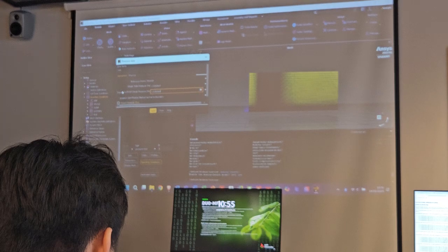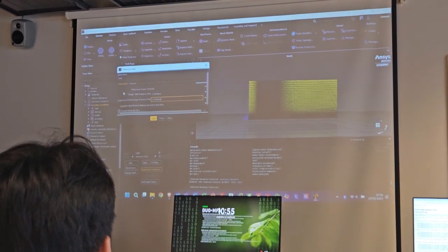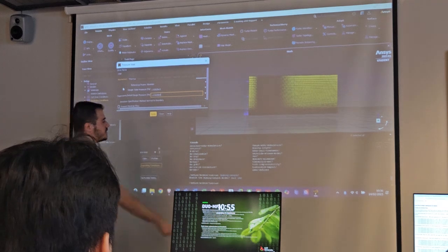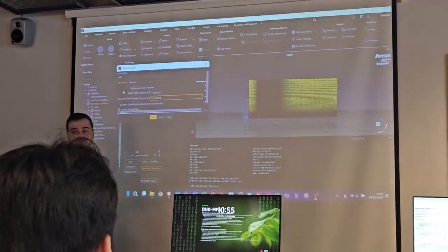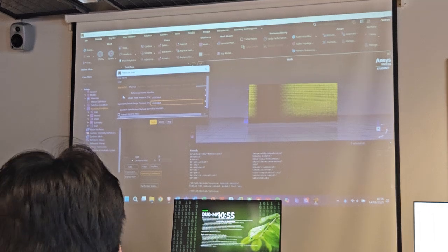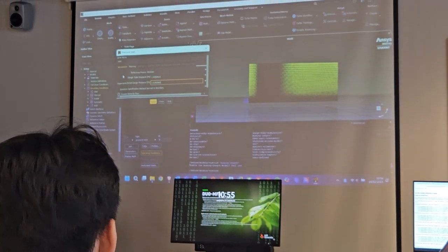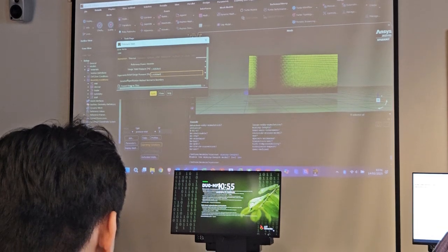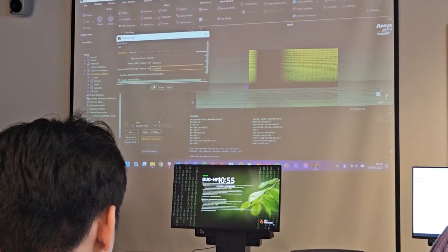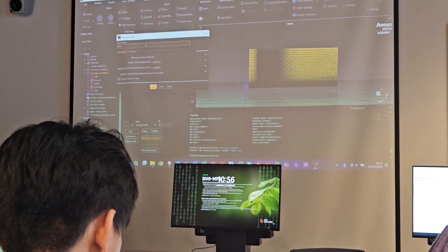Then you can prevent reverse flow or not, it doesn't really matter. Reverse flow means that there is flow actually exiting the inlet. If you have problems with your simulation, that could be an option to avoid that problem. But if you set up correctly, you don't have that problem. So we don't need it, and we can hit apply to save this modification.